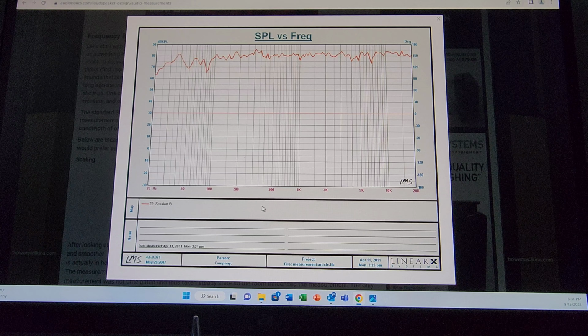So right here, this is the orb, and this green line up here would be the cone diffractor. That's actually about a 7 dB gain just by changing the shape over top of the speaker, which certainly goes to prove that when the speaker interacts with its surroundings, whether it's a diffractor or whether it's the room, we are going to get a different response.